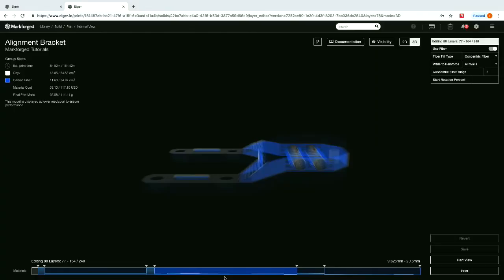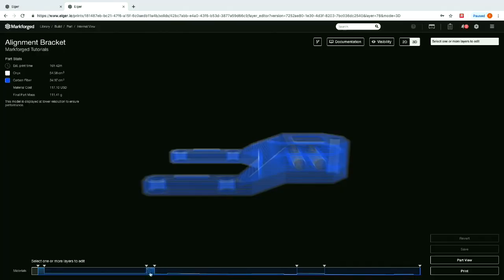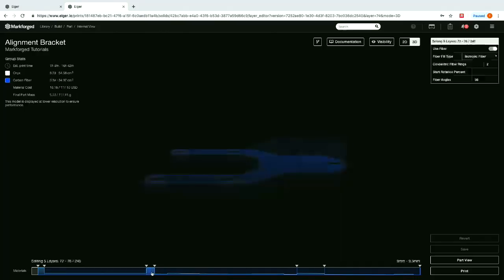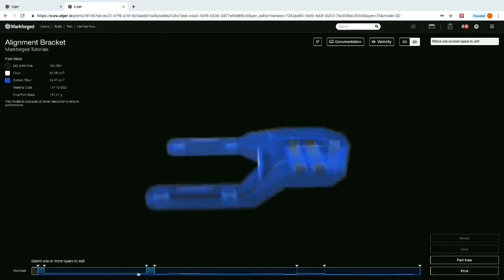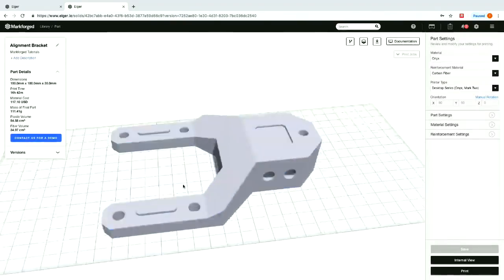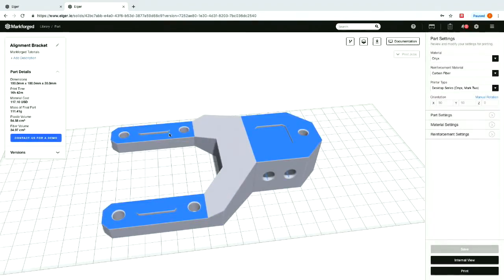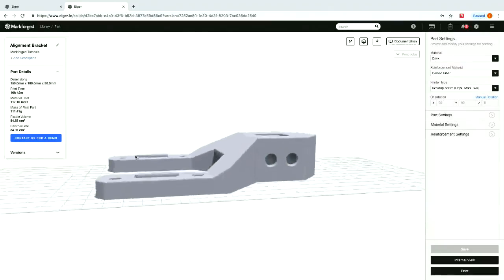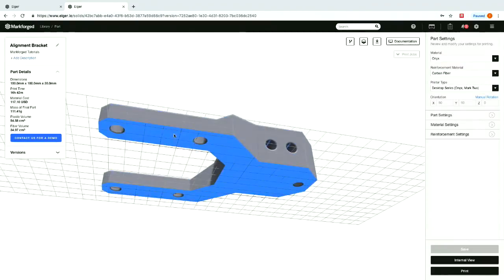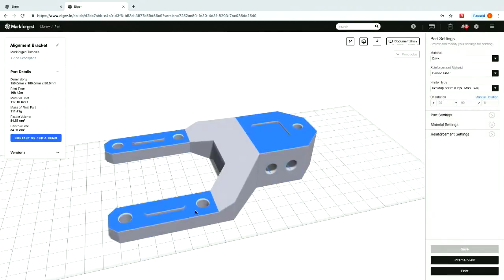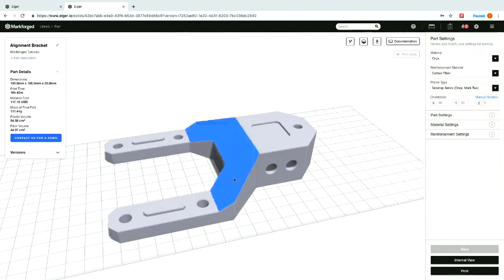The other thing we'll see is that you can reinforce unique features. In this reinforcement here, the reason this is done isotropically is because we want to reinforce, it's easier to see in the part view, basically this top surface of this bracket because we believe it's going to be bent. So we're creating a sandwich panel on the bottom face and the top face, which makes this part of the bracket super strong. The other part is fiber reinforced with concentric fiber, but the top and bottom here are critical.